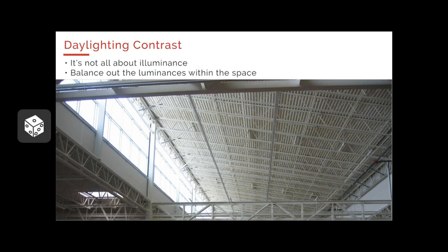Of course, the result is that they loved the clerestory window approach because the ceiling was brighter, versus the skylight approach, where the ceiling next to it is extremely dark and there's too much contrast. So this is an effective way. And again, to make this work, try to get those clerestories oriented south as much as possible.